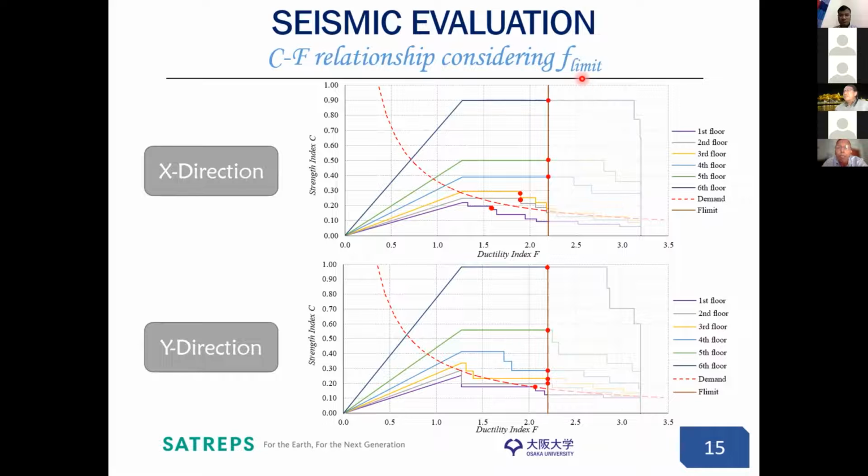But since the building had some certain criteria that it ticked off, we are penalizing the building, saying that there exists a probability of pull-out failure if we consider any performance of the building in these parts. So we are simply ignoring that capacity, which might be there, but might also come with a penalty of such kind of pull-out failure in some of the joints. So in this case, now we will judge if the capacity of the building satisfies the demand.